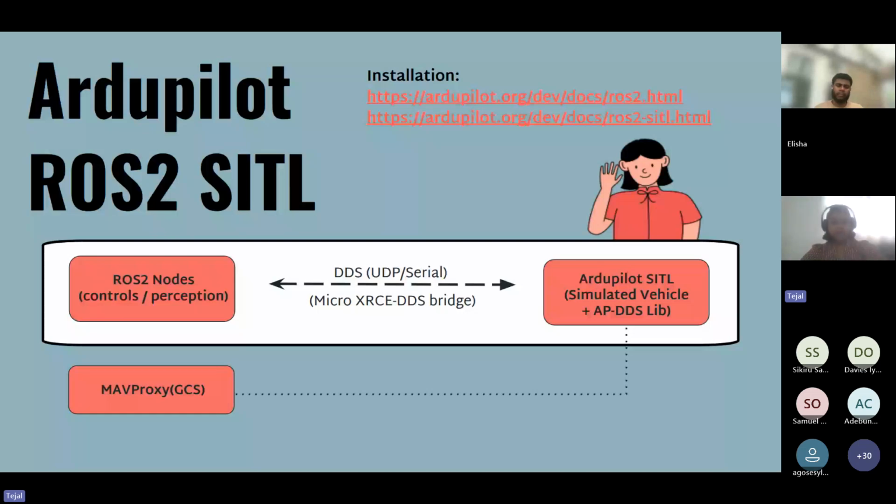Now, when you create ROS2 nodes on the companion computer, there are several clients created. These clients actually communicate to the server present on the microcontroller via the micro XRCE DDS protocol. And therefore, this micro XRCE DDS library becomes a lot more important. We'll see this again when we go over the tar file tutorial that we have.